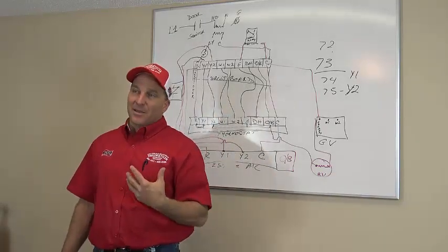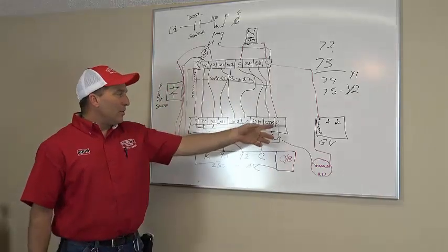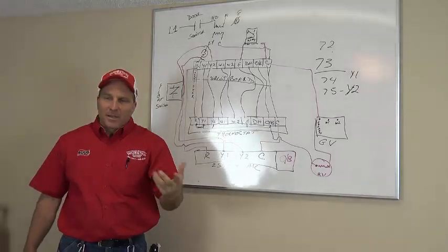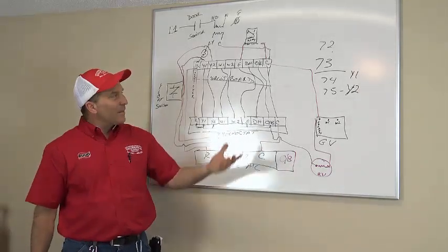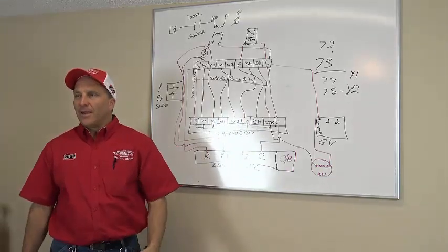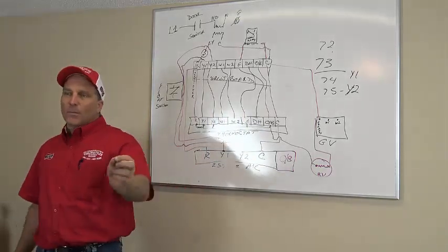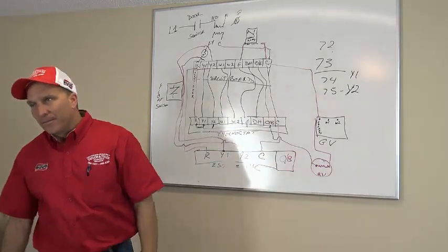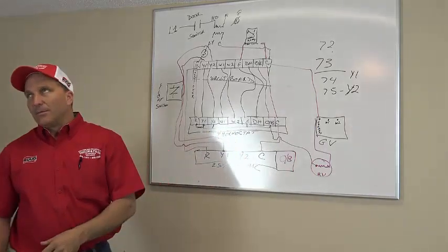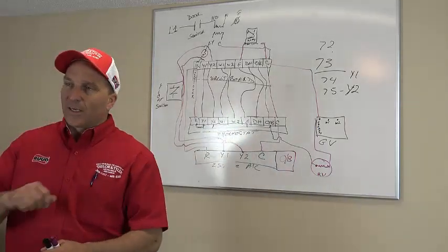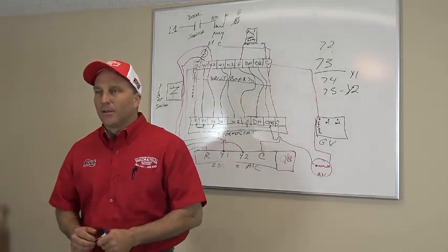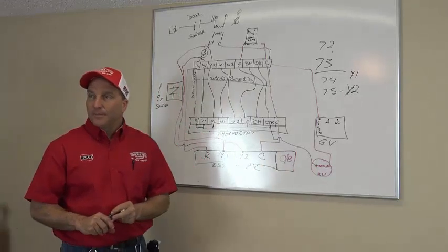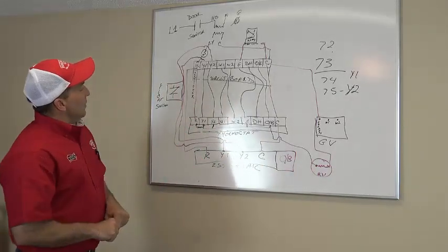And when he explained it to me like that, I went, oh, the O's energized and the Y's energized. That's how I'm running my air conditioning system, and it goes backwards. Oh, how does my heat strip kick on? Well, that's second stage. Oh, when you go to emergency heat, it kicks on W1, and Y1 is not energized anymore. Does that make sense? Did I clear up some of that for you in your head? Okay, good.